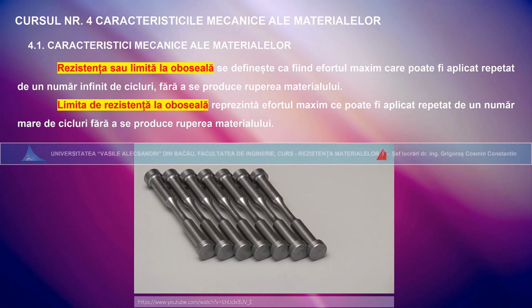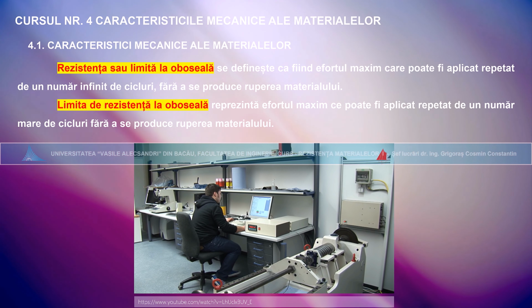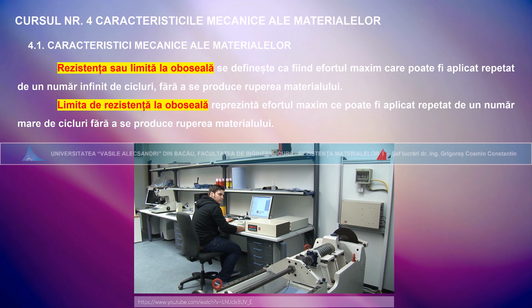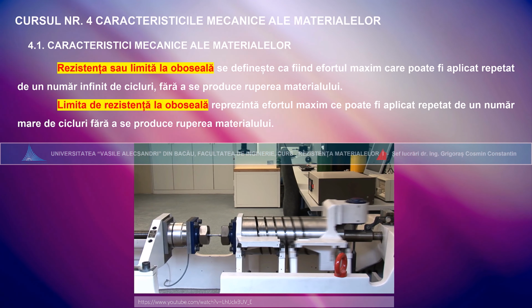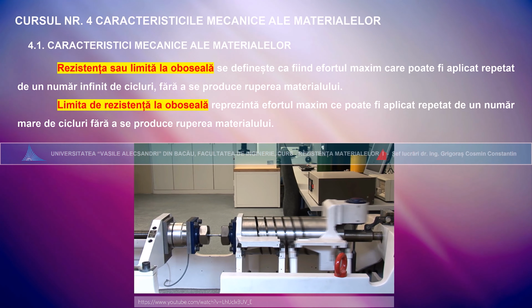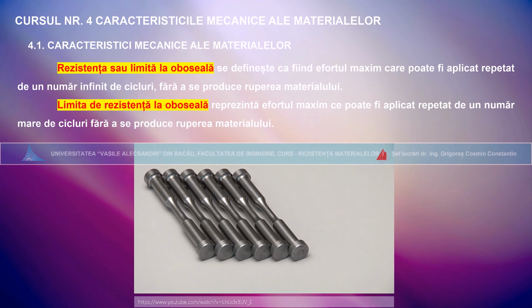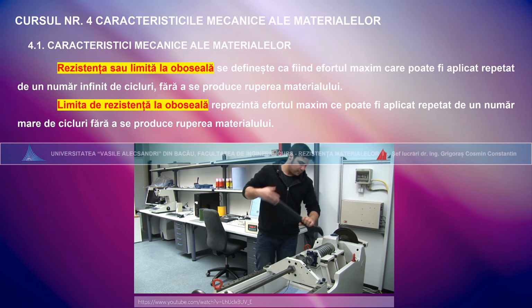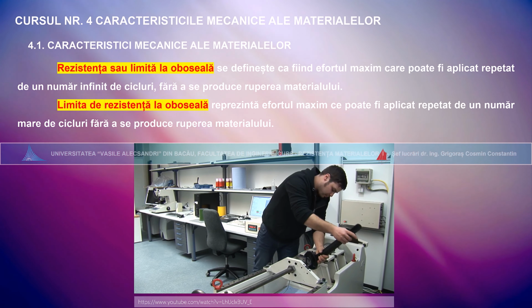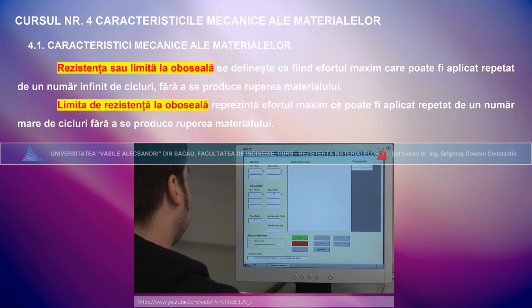The third specimen is only tested with a cyclic load of 6.5 kN. Under this reduced load, it does not break even after 3 million load cycles. Additional specimens complete the series of measurements. Some of the specimens are tested with the same load we've already used. In this way, we get an impression of the range of scattering.